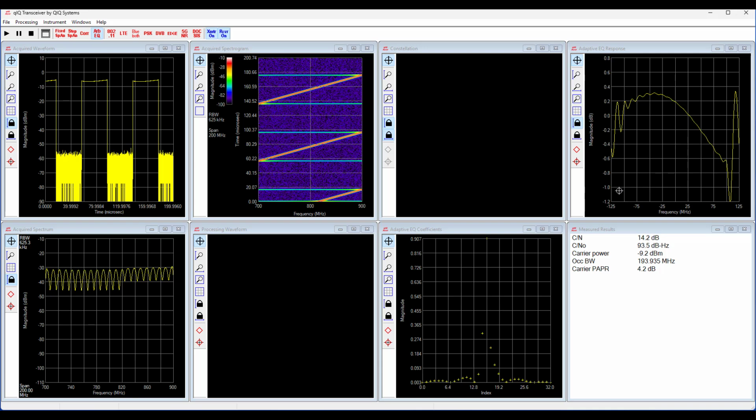This plot is displayed from minus 125 to plus 125 megahertz. The reality is the chirp is there just from minus 100 to plus 100. So we focus our attention from here to here on this plot. And you'll notice that it tends to roll down this edge, the higher frequency part of the thing. It actually initially rolls up and then it rolls down, because that's what it needs to do to compensate for the system response that we're trying to equalize away.